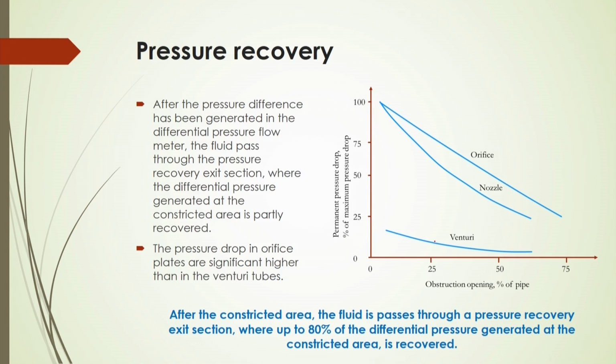So, in that case the pressure drop in the orifice plate is significantly higher than in the Venturi tube. You have to remember this: the pressure drop in the Venturi will always be lower than in the orifice plate, and you will see the same in the nozzle.